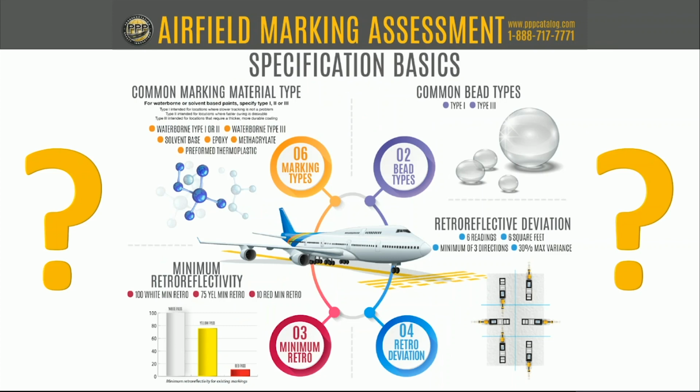Yeah, thanks for the question, Tim. Just to clarify, type 3 is not allowed in red or pink markings, and those red or pink markings on the airfield, particularly on the movement area, are your red surface painted holding position signs at a runway intersection and your geographic position markings. Those are the pink circles, the pink spots.